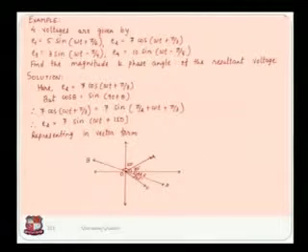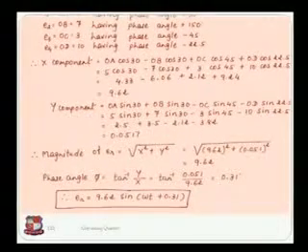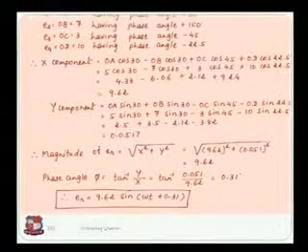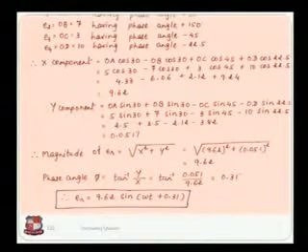Now you have to find the resultant voltage. So again, same method, you have to use the resolution method. So E2 is equal to OB is equal to 7 and the phase angle is equal to plus 150 degrees as shown in the figure. For E3, the magnitude is equal to 3, which is represented by OC and having a phase angle of minus 45, and for E4, which is represented by OD, the magnitude is equal to 10 and having a phase angle of minus 22.5. So now we have to find the X component of all the 4 currents.